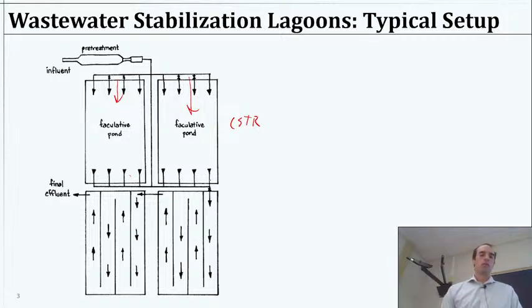And then down here, we see they have it more channelized, so this is acting more like a plug flow reactor. And here you could section part of it off and say, okay, I'm going to let it go anaerobic for this portion while it's in this area, and then re-aerate again before the end. Things like that type of design are common. Of course, that'll be up to the designers to say specifically how they are meeting their treatment goals. But those are the types of options you'll see in play.